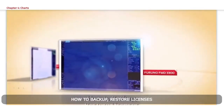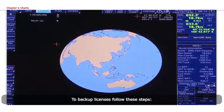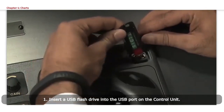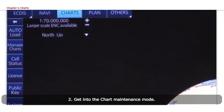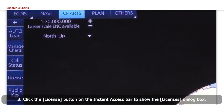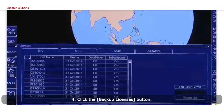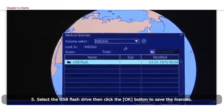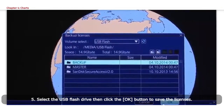How to backup, restore licenses. To backup licenses, follow these steps. 1. Insert a USB flash drive into the USB port on the control unit. 2. Get into the chart maintenance mode. 3. Click the License button on the Instant Access bar to show the Licenses dialog box. 4. Click the Backup Licenses button. 5. Select the USB flash drive, then click the OK button to save the licenses.